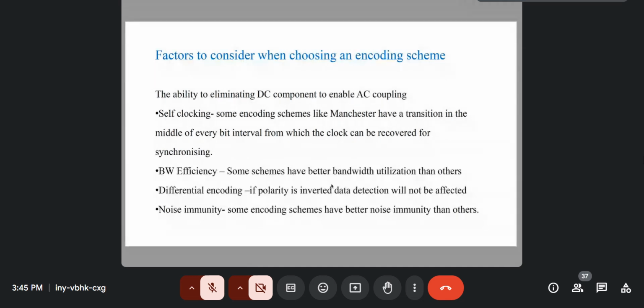So you have different symbols carrying different bits. For example, for QPSK, which we are going to look at, you are transmitting 2 bits. So you have symbol 1 carrying 0,0, symbol 2 carrying 0,1, symbol 3 carrying 1,0, and so on. So you need 4 symbols to do that.